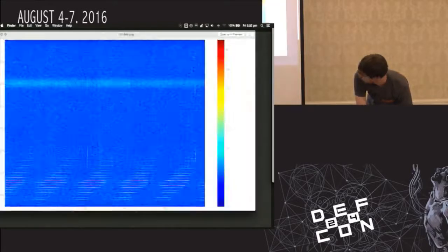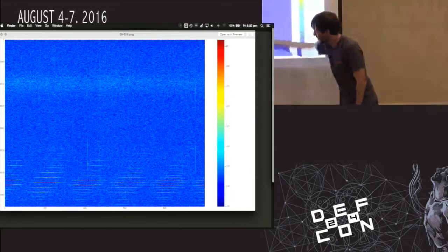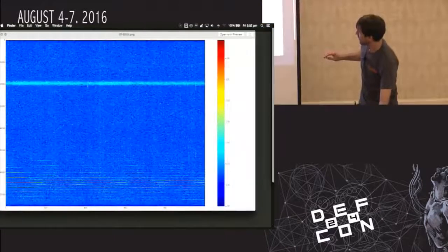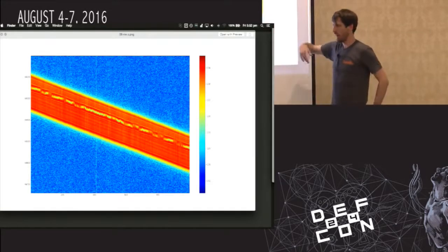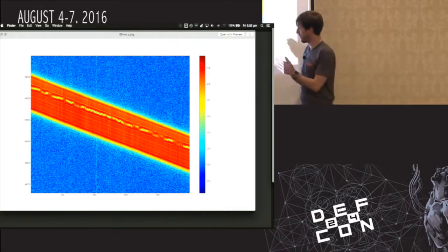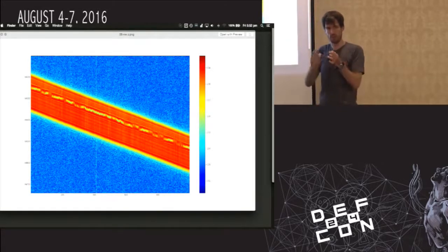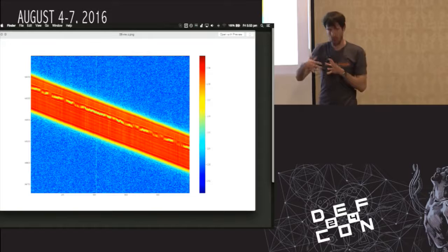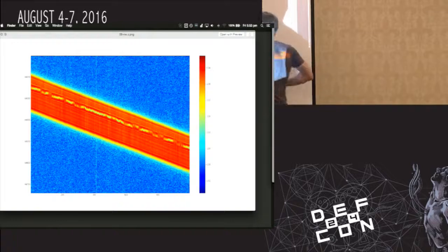So again, we've got our sidebands there, AM, though you can't see them due to aliasing. If you actually zoom into one of them, you can see this thing. This should be straight, and in this case I wasn't using a GPSDO, so I have to go back and reprocess everything and do some fine frequency offset. I think I calculated that at each step I was losing like 0.02 hertz. So even at that tiny amount of frequency offset, it ends up producing this visible offset over time, which is why you need to lock and integrate and make sure that you round everything up. But you can see stuff moving there in the middle.